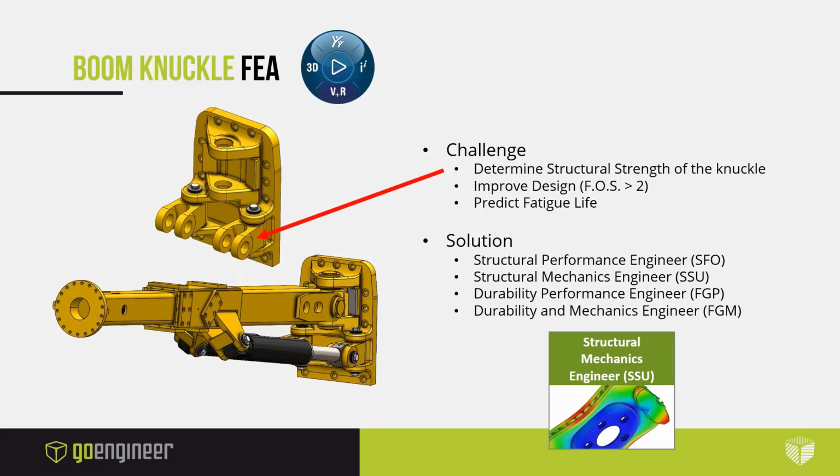Now, besides that, I'd like to demonstrate some of the fatigue analysis technology that we have access to. So I am testing this for multiple cycles. I'm testing this for not only static conditions, but also for survival. Now, as far as the solution goes, we have multiple solutions for structural analysis on the 3D Experience platform, but just know that the commonality these all share is they're all based on the Abaqus solver. Each of these solutions gives you an additional level of capability as you step through them. So for instance, the structural performance engineer gives you access to the standard implicit solver, while the mechanics engineer gives you access to both the explicit and the implicit solver. So all of these refer to the same technology, but just at different levels.